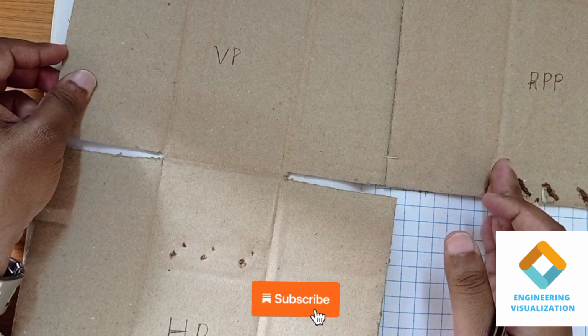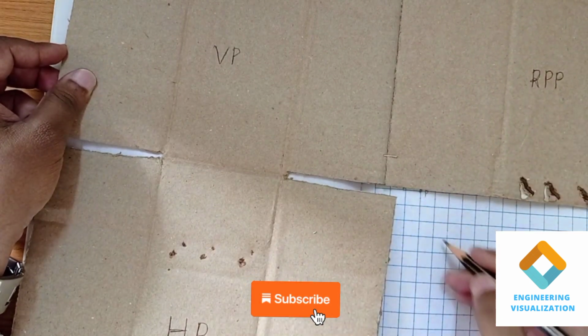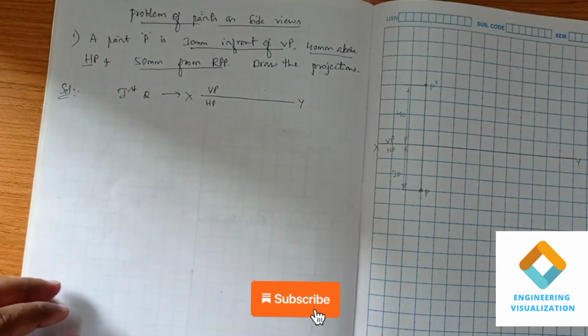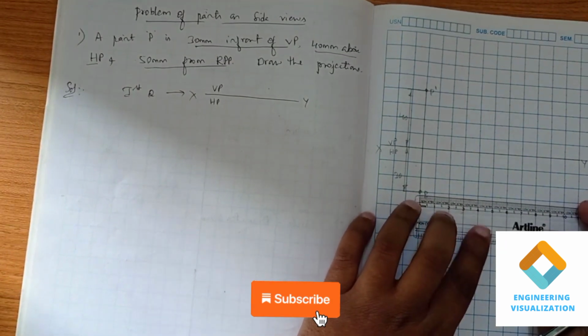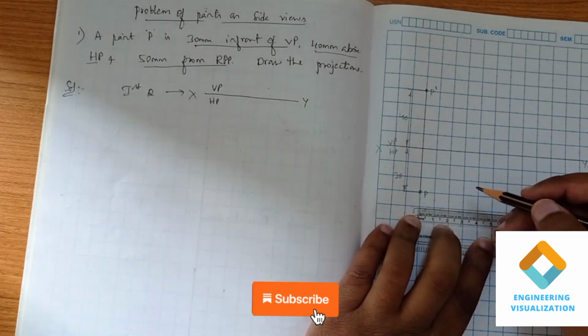mm. Now to draw this side view with the top view we will be using a 45-degree angle line. So you just follow the procedure. Now from this projection point we have to consider a distance of 50, that is 5 boxes.